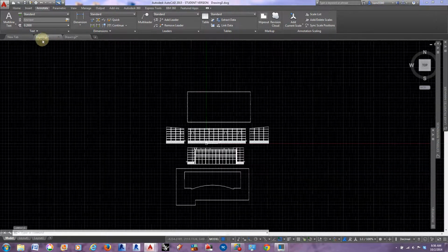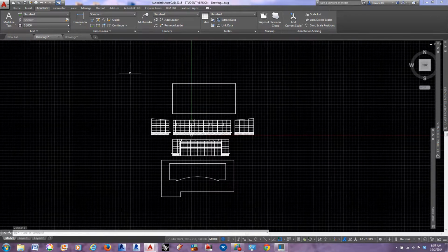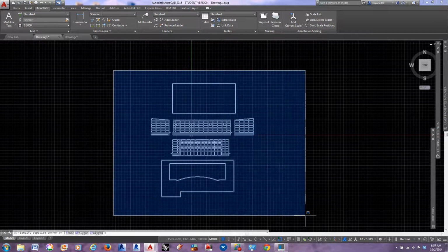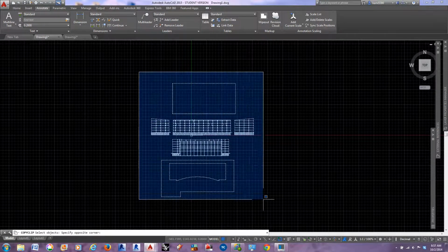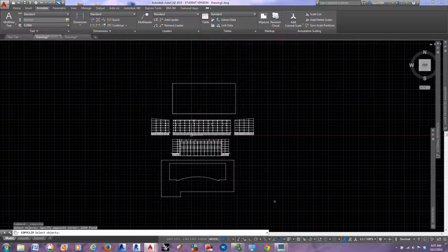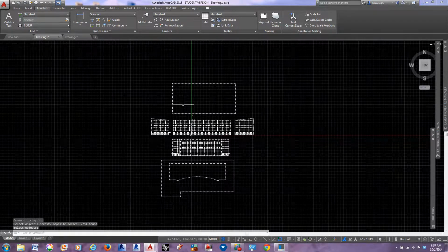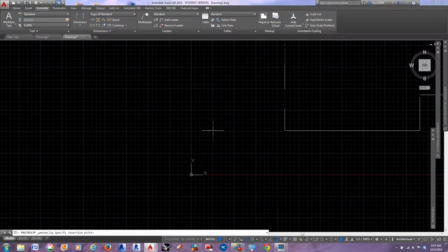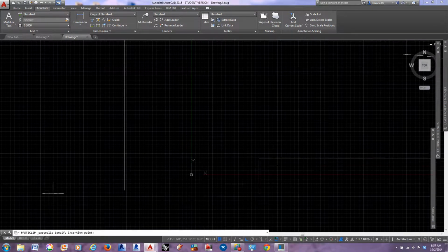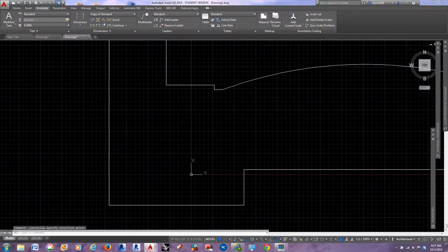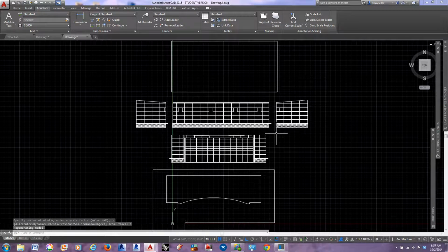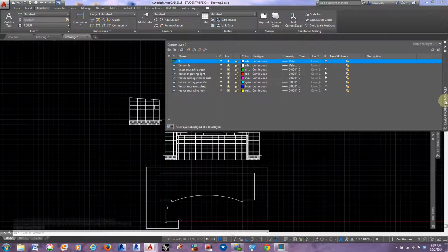And we're going to go back to our DWG file that has all of our line work in it, and we can select it and Control C, then select it and hit enter to copy it to the clipboard, and Control V, paste it, switching to our template file, hit Control V and Z all, so we can see that all of it is now in our template file, and we don't have any other extra layers that come in, because we put it on the 0 layer which already existed.